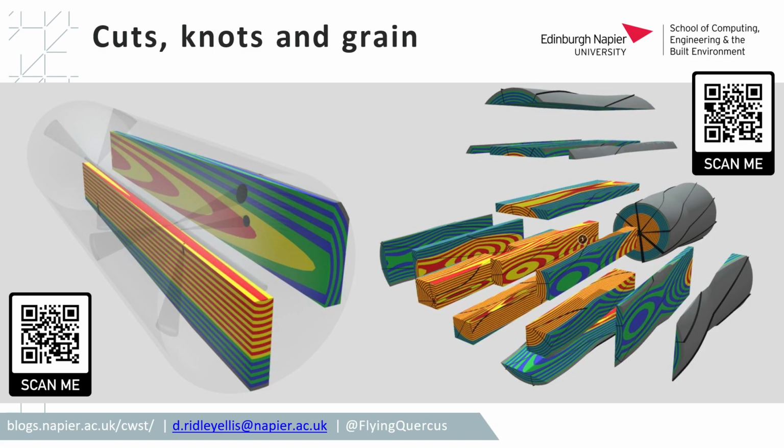That makes sense. So for example, quarter sawn wood. Example of quarter sawn here, there might be. Really, quarter sawn wood, I'll show you later on. Quarter sawn wood is the perfect material for making furniture out of, because it's going to have very little movement of moisture, of dimensional stability, the way how it's been cut. It's unlikely to warp and twist.